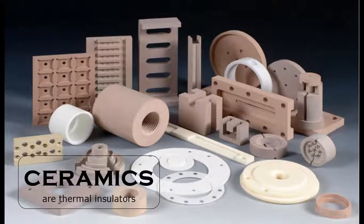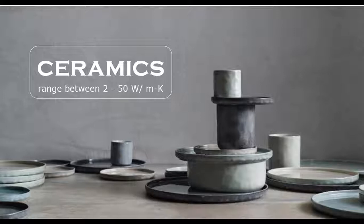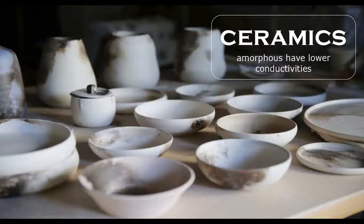Now let's proceed to ceramics. In terms of their thermal conductivities, we also have to consider three things. Firstly, they are thermal insulators, as they lack large numbers of free electrons, which is contrary to the metals. Secondly, the room temperature thermal conductivity of ceramics ranges between approximately 2 to 50 watts per meter Kelvin. Lastly, amorphous ceramics have lower conductivities than crystalline ceramics, as atomic structure is highly disordered and irregular.